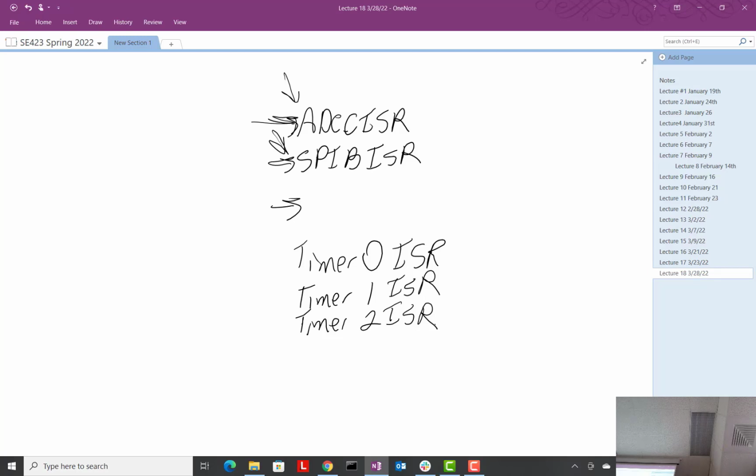In other words, what's the latency? If we tell the timer that we want to sample, if you're doing the microphone, maybe you're doing it at 10 kilohertz. And so every 0.1 milliseconds, you say, hey, I want to call timer 0. Right? We don't want too much latency in between there. When we tell it to go, it's got to be in priority.